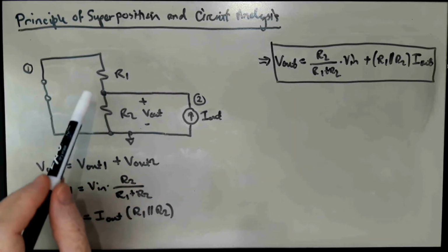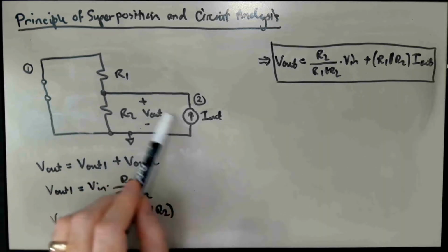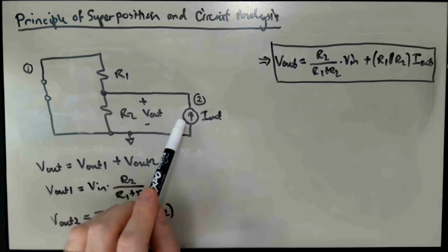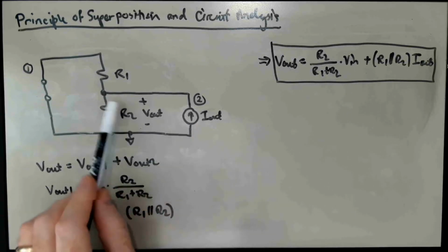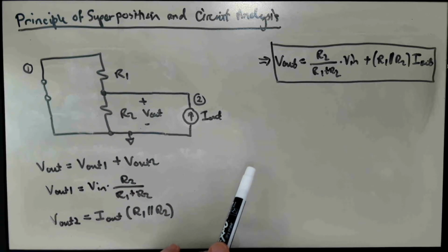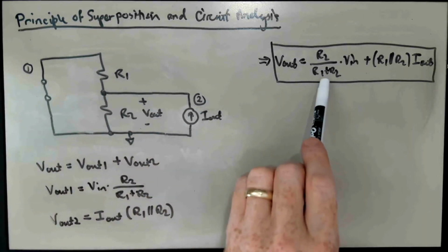Right? That's the way the voltage divider is usually set up. But if we actually have some current that has to be supplied to some load connected to this middle node, the question is, how much does that current shift the voltage away from the desired value that we pick by whatever the total voltage is here times the voltage divider ratio?